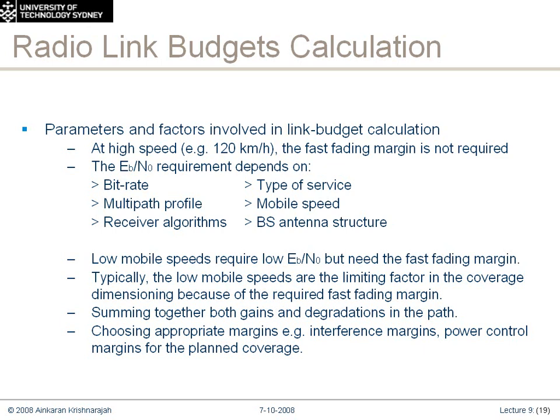So if you can imagine, you're trying to model mobile phone coverage in Tokyo on the bullet trains, for example, across their train lines, so that consumers can make voice calls as well as download high-speed data. You need to take into account the speed of the consumer or the subscriber, as that has an effect on the fast fading margin as well, which is essentially around the attenuation at the end of the day.